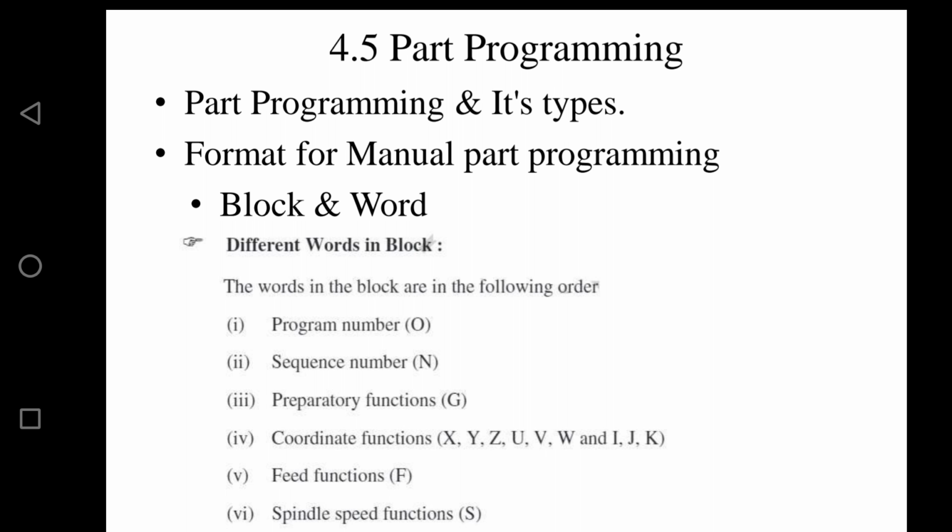A block is a group of words for feeding the NC and CNC machine systems to execute a particular movement of the tool. If I want to execute a particular movement of the tool, I need to feed my program to the NC and CNC machines, and that is written in the form of blocks.